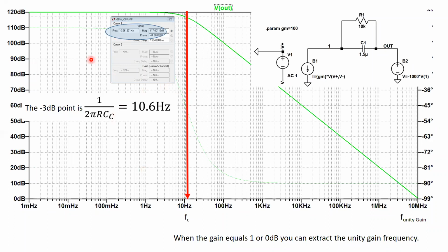So the thing is if I'm working in this area with a gain of 10 dB, right? Right up here where it's 20 dB, right? So the thing is, I can go up to 100. Well, let's be conservative. I can go up to 100 kilohertz with a gain of 10 dB because the open loop gain at that frequency is 40 dB.